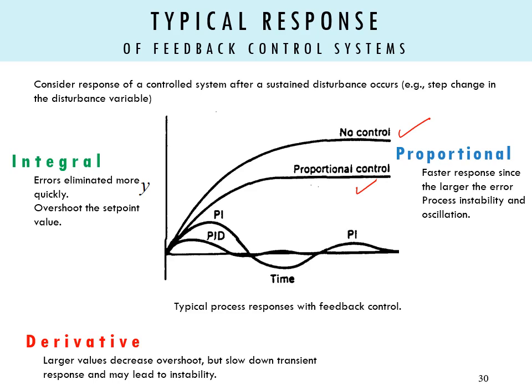However, a faster response requires higher proportional gain, thus contributing to higher error and instability in the control system. The integral term discards the error produced while having the overshoot and reaches the set point eventually, as shown in this figure. And the derivative term in the PID controller reduces the overshoot in the output response. However, the output response becomes slower, which leads to instability in the process control system.